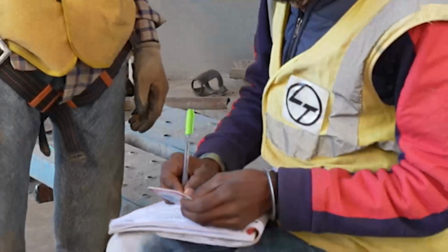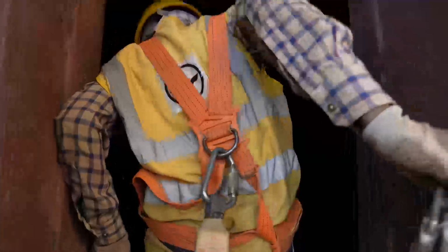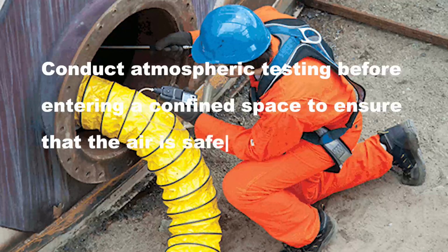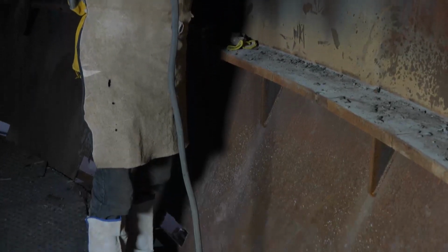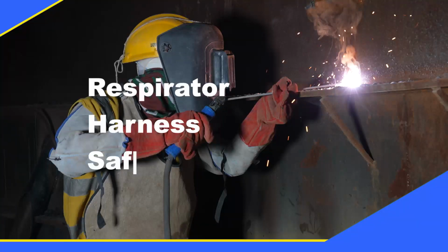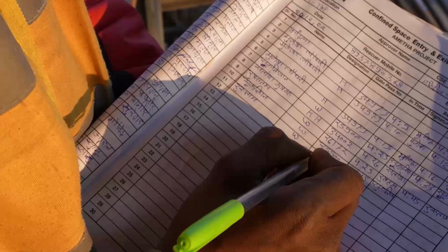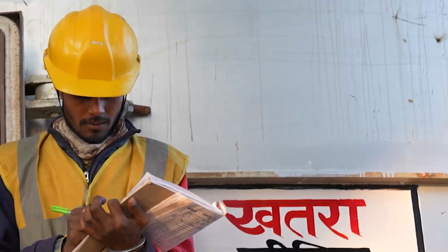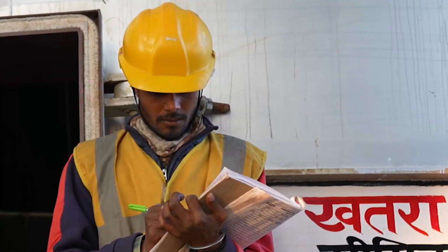Obtain proper training and authorization such as work permit before entering a confined space. Conduct atmospheric testing before entering a confined space to ensure that the air is safe to breathe. Use appropriate personal protective equipment (PPE) such as a respirator, harness, and safety glasses. Maintain a record of entry and exit of all workmen entering and exiting the confined space. Depute one attendant at the entry of the confined space who knows and is trained in the rescue process.